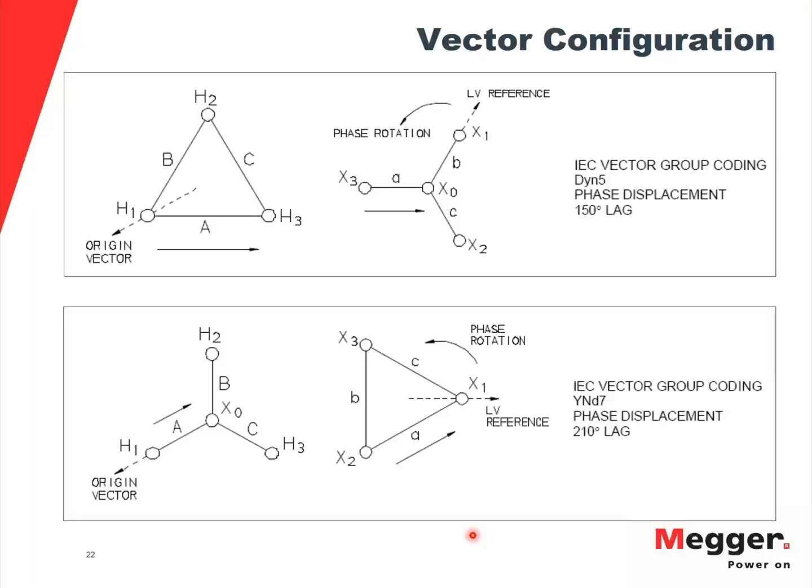That's a very good question, and the reason, with the limited time we had, we were not able to go that in depth. But think about this one, that you have a Y winding, and I'm assuming you're talking about winding resistance. So if you have Y connection, if you have auto transformer and Y connection, you can either measure from H1 to H0, or you have the option of doing H1, X1, and then X1, X0.